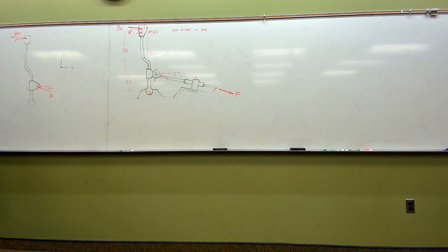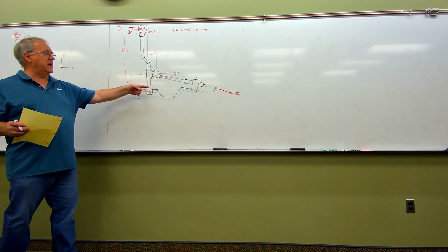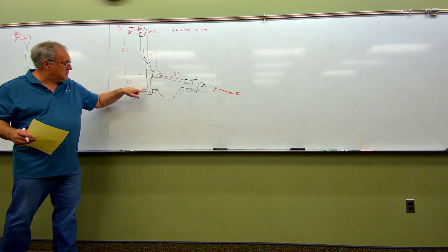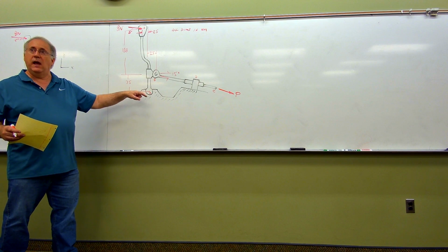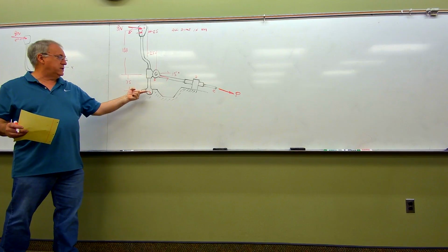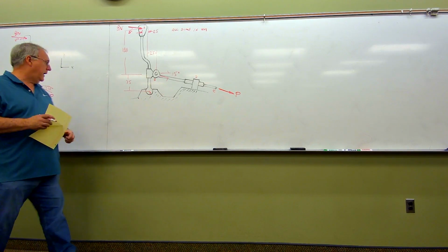So now, with that, I've got the force here, where I used to be in contact with something. I used to also be in contact with the ball, the socket for the ball down here, but we haven't seen one of those yet, right? We have not seen one of those. Here's where that ability to say, okay, when I don't know, I can trust the idea that I can ask myself, could I translate this in the X direction, and would I face resistance to motion? So if this thing here really was embedded in that socket joint right there, and I try to move this thing here in the X direction, would I face resistance to motion? Sure. So I'd have an X force.